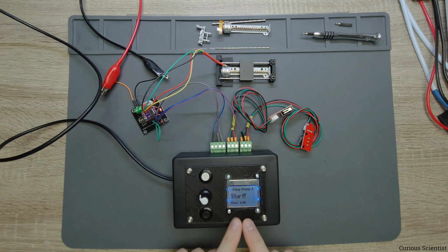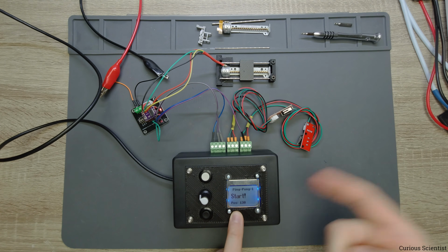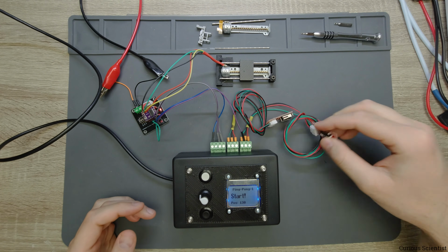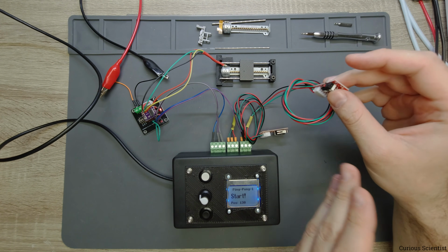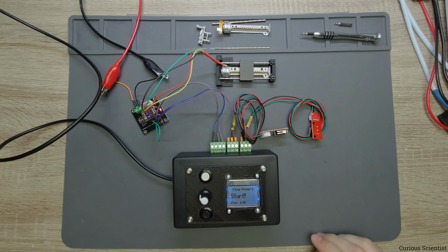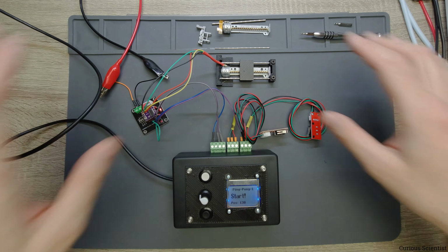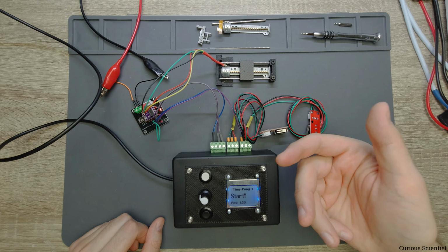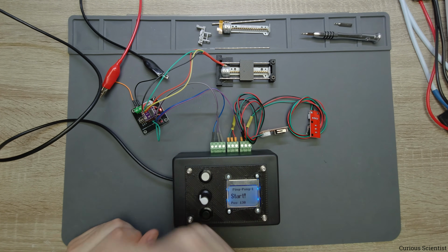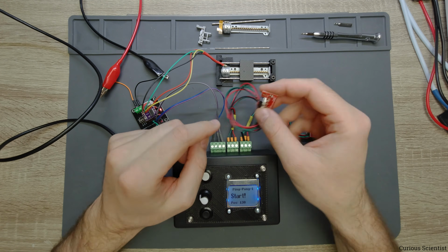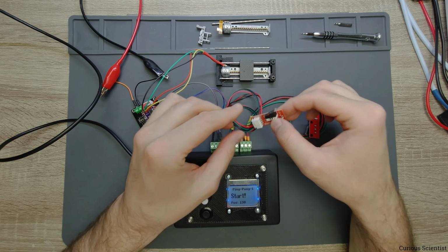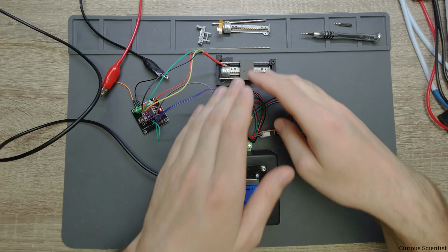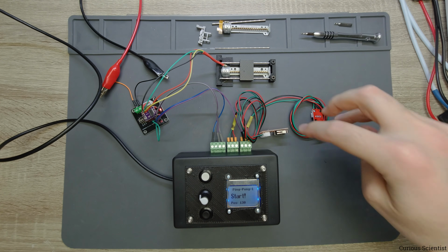What this does is that the code runs, and then it goes towards the positive direction as long as it doesn't hit the limit switch at the positive end. So let's say on the right hand side on the screen, but again this depends on how you set up the system. And then when this limit switch is hit, it flips the direction and it starts to go the other way until you hit the other limit switch. And then when this limit switch is hit, it flips the direction and goes towards the other limit switch. So it doesn't take care about anything else, just the limit switches.